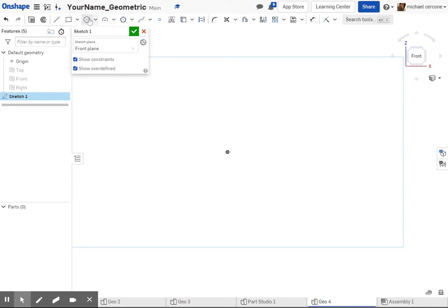Now I know that there's a circle in the center, and this whole thing is pretty much built up off of the origin. So I'm going to probably start by drawing that circle in the center, and then a couple construction lines. This is a 3 1/4 diameter, 3.25, just to define that. And now I'll draw in a construction line.